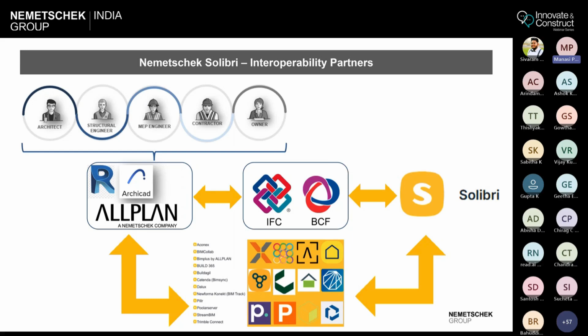So all the AECO stakeholders from architectural designers, structural, MEP, contracting teams, and the owner teams or PMC teams, they are using one or the other popular BIM tools like ArchiCAD, Vectorworks, Allplan, or Revit. All of these files definitely have IFC translators today, and good quality IFC schemas are being extracted, and those are pushed to Solibri. So that is the first step of how all these different models can still come into Solibri.